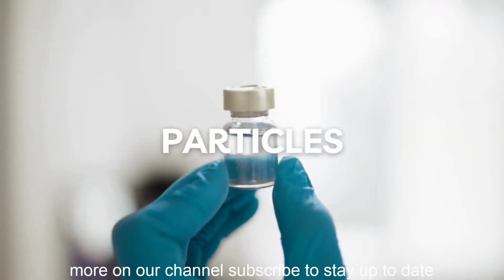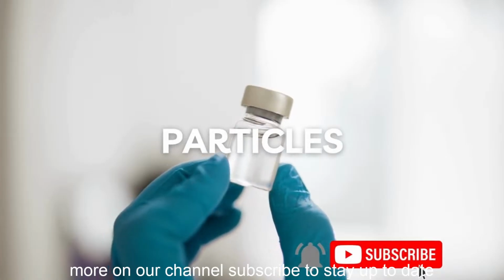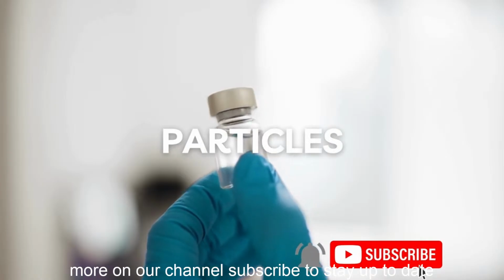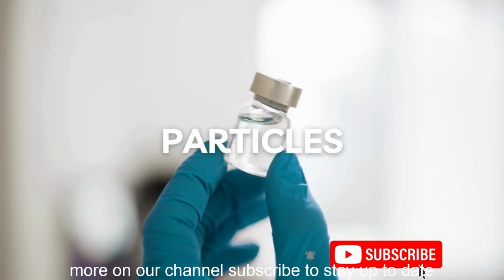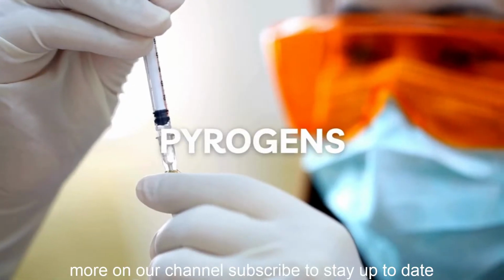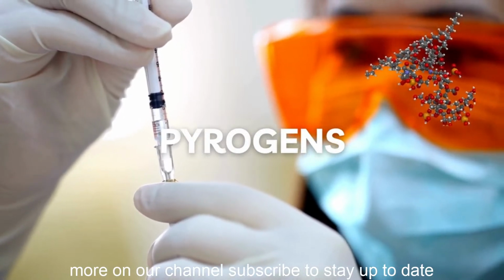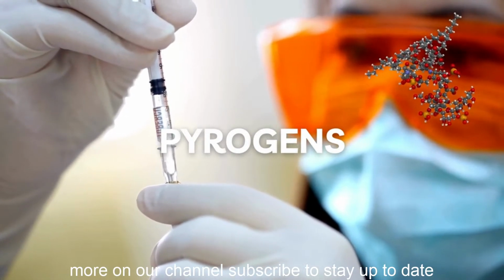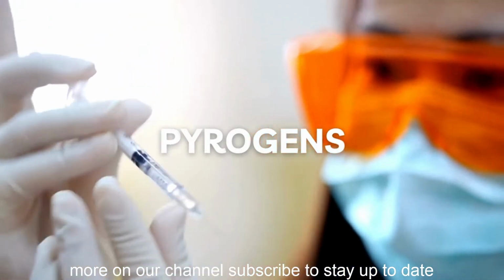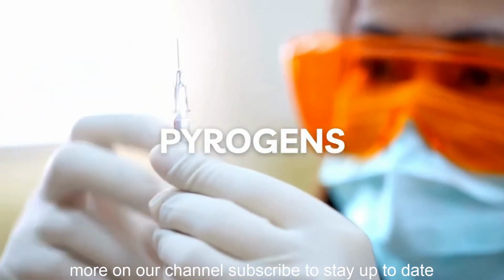Particulate contamination. This involves the presence of unwanted particles in the final product, such as dust, fibers, and other debris. Annex 1 addresses this by requiring the use of appropriate clothing, controlled environments, and online particle monitoring systems. Pyrogen contamination. Pyrogens are fever-inducing substances, often derived from microorganisms. Annex 1 highlights the need for water quality control (WFI, water for injection), depyrogenation processes like dry heat sterilization, and the proper handling of materials to prevent pyrogen contamination.